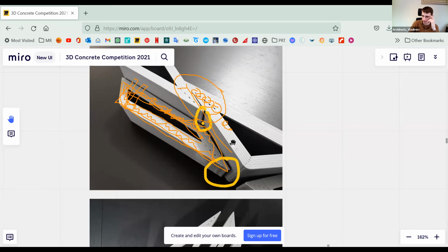So there are 2 choices: fill or not fill. You should make the choice from a design point of view, not structural, because structurally it's not important. Maybe we should think that if we fill it, it will collect water or something else, and the beams will not dry so well.